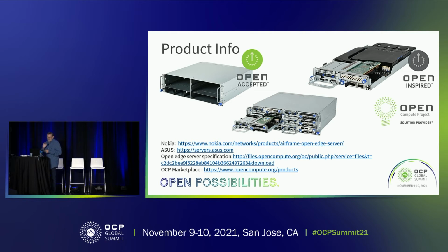Power supplies can come in 3-phase, single phase, DC, negative 48, depending on the power supply, and that converts it to a 12-volt bus. What you can't see in this particular view of the chassis is there's a power distribution board that takes the input from the power units and then distributes that up to a backplane riser that has those DC bus bars that the server sleds plug into, that Raymond spoke of when he showed the connectors in the rear. Those 2 connectors in the rear, one is signal and one is power, and it has a guide pin for alignment.